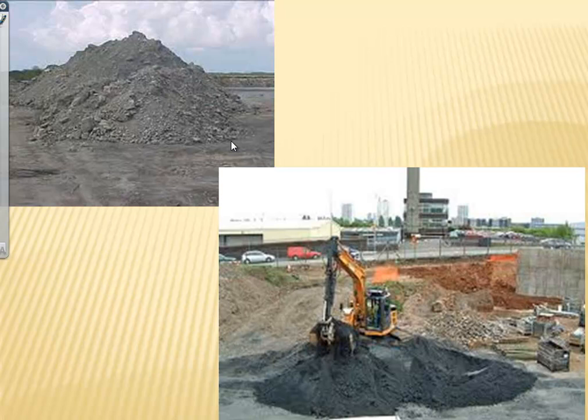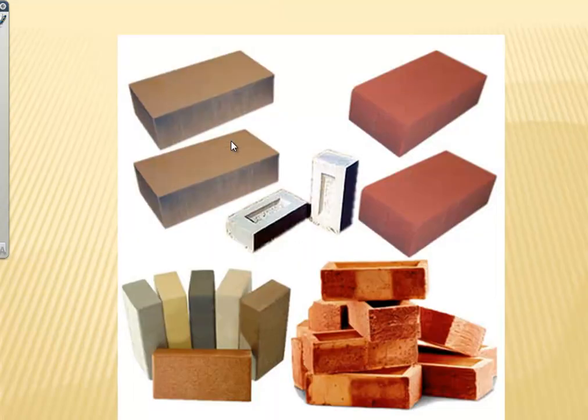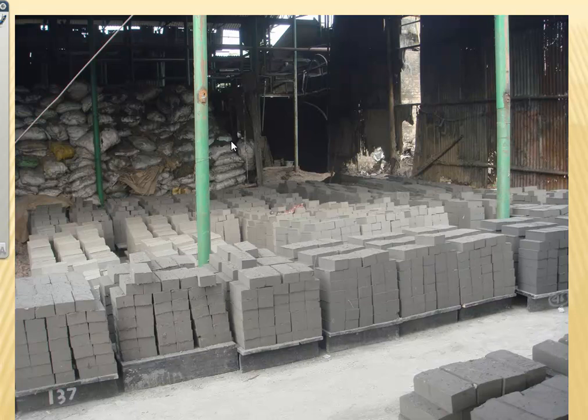This is bottom ash. The top left is bottom ash, which gets taken to a landfill. The bottom right is fly ash, the stuff that was cleaned out of the exhaust, either through the electrostatic precipitator or through the scrubber. What do we do with that? It's toxic. Well, we created a very unique way of recycling it. We make it into bricks and concrete blocks. Yes, fly ash is actually put into concrete blocks. So instead of disposing of it, we put it into our building materials.